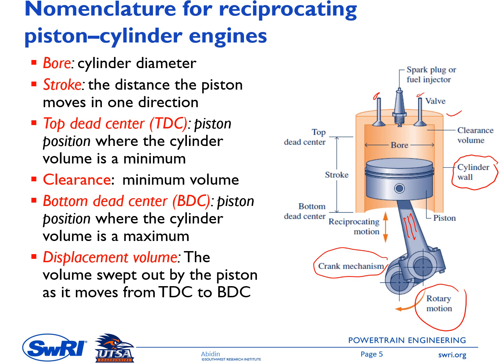once the piston is at the maximum location at the bottom side, it will move back, so it moves up, and then the intake valve closes, and then there will be a compression there. So this is the second stroke, which is the compression stroke.